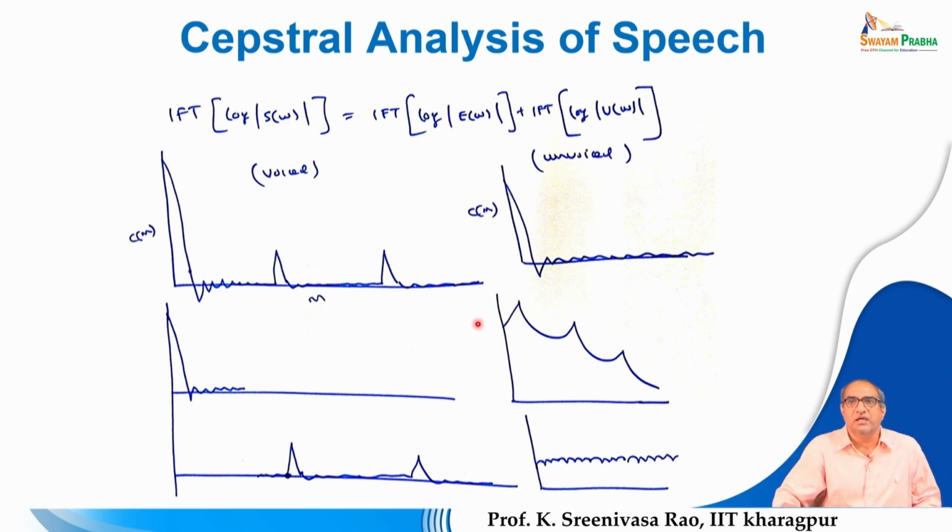So this way one can analyze the excitation component and the vocal tract component of a speech signal separately, so that after separation we can use the vocal tract response or properties for discriminating various things, like speech sounds, speaker characteristics, or language-specific information. Those tasks you can perform in a very seamless way by analyzing the cepstrum, or rather the initial samples of the cepstrum, which are more specific to the vocal tract system.